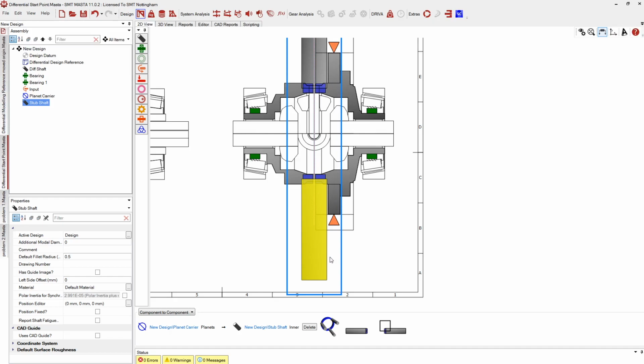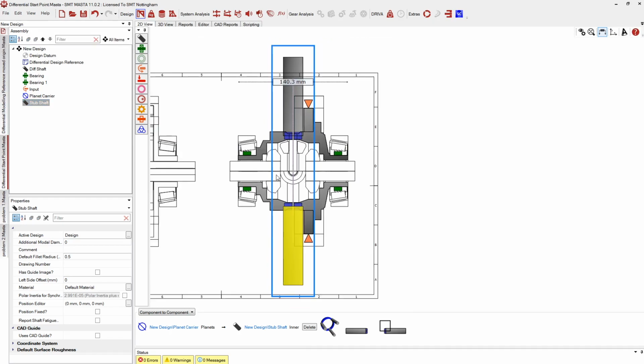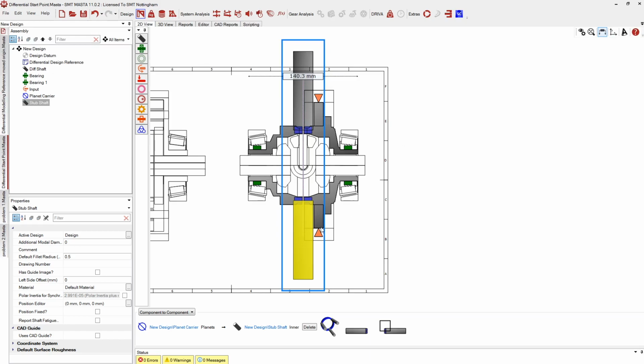It's switched orientation. It's now being modeled top to bottom. And you can see that it's already been duplicated as well. So I've created this one basic shaft shape here, but it's been duplicated at the top as well to show us that it's a repeated system based on a per planet basis. So if you've got 3 planets, it will repeat 3 times and so on. And if I move that, you can see how those two interact.